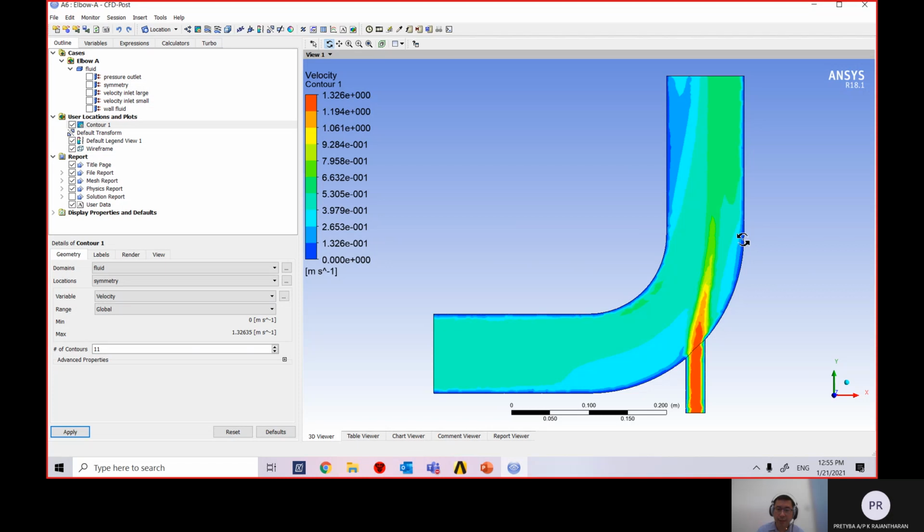If you project, you will see how you read these results. Velocity is plotted from minimum to maximum. Red color is the maximum. So on the graph here, you will see that it matches what we learned, meaning that at the surface of the pipe, there's no velocity because of the viscous effect. And also the maximum is here because we have a small nozzle. We agree with experiment and observation.